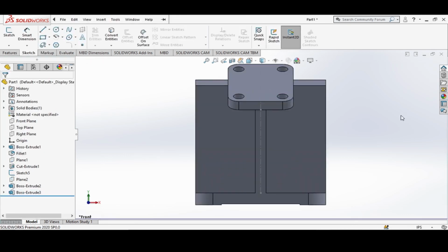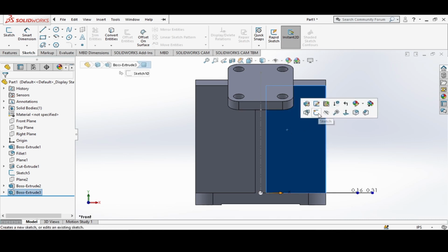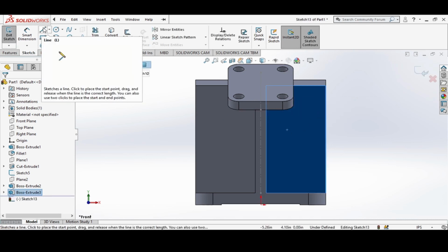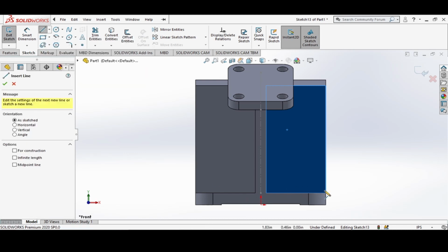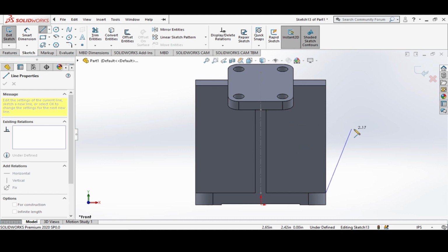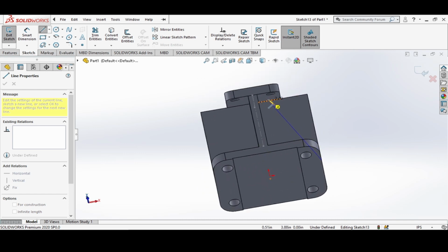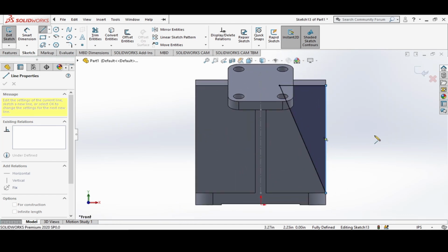Now by setting our sketch into its front view, we can now draw a rectangular shape on this part of our sketch. Just click it and then choose sketch. Then use a regular line and start here up to the midpoint of this particular line. Then here and back here. Now we have a rectangular shape.